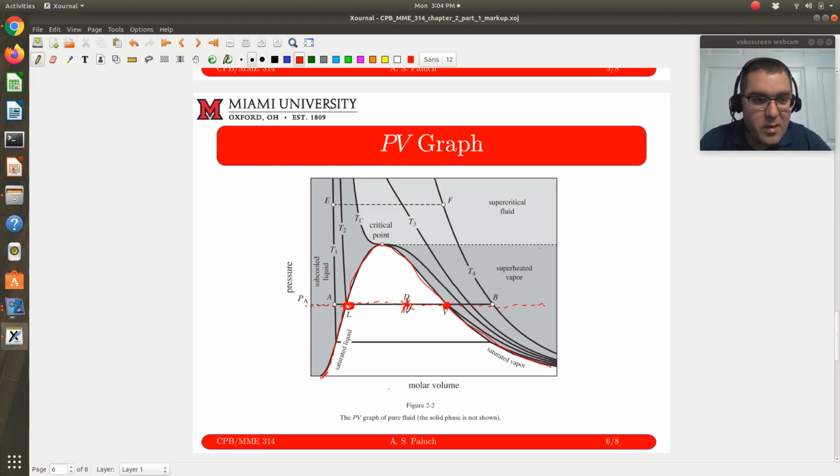Underneath I have a two-phase liquid-vapor system. Well, what do I have outside of it then? First, I want to look at one more reference point before we jump to that. I should mention, I said if I specify my volume and it puts me underneath my dome, I know I'll have phase splitting.